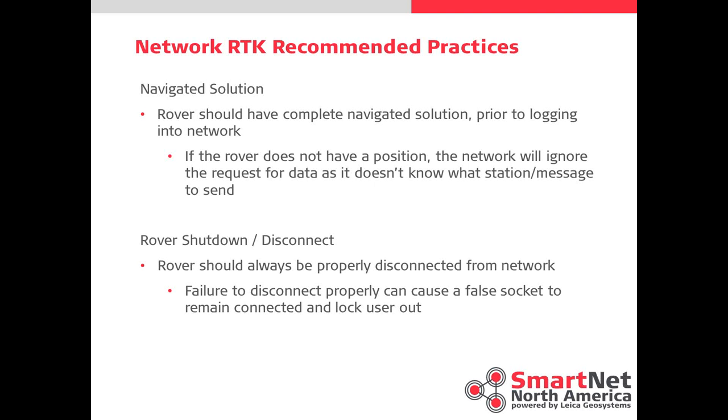So if you're accustomed to being able to just connect in and then start getting corrections without having a solution, you're going to have to go outside, or you're going to have to at least have 5 satellites and a navigated solution prior to connecting into the network.